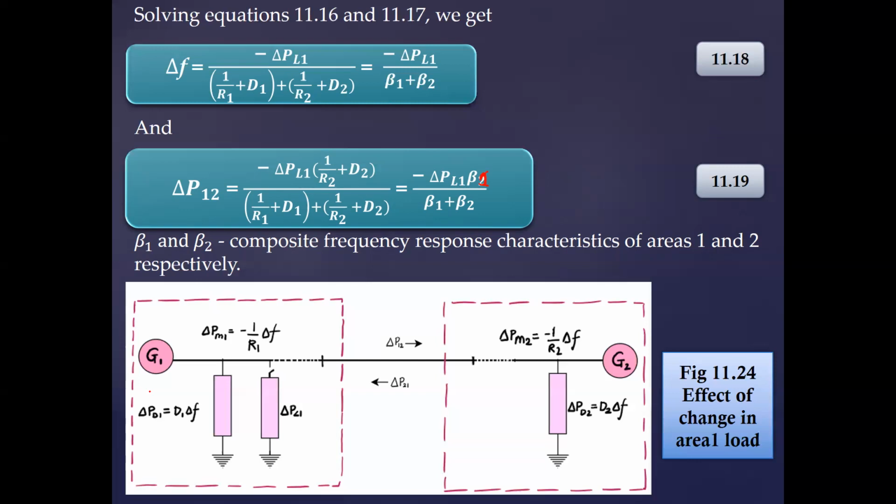So the generator you select to apply the secondary control is the most economical one for that generation? Yes, we do it. So where if I have renewable sources, for example, solar PV or wind in my system, in that case I will prioritize taking the power from them, rather than taking the power from conventional fossil fuel or gas turbines, right?